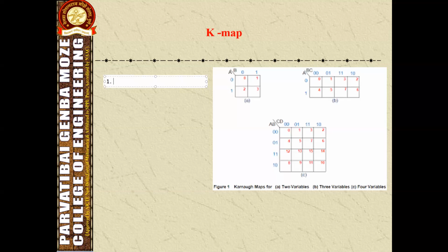Let's take a quick overview of the rules of the K-map. The groups may not contain any zero. According to our truth table or excitation table, we fill the number of ones into these K-maps. These represent the values of the K-map, and these are the variables, with the bar as the variable complement. After filling the ones, the grouping of the ones takes place.